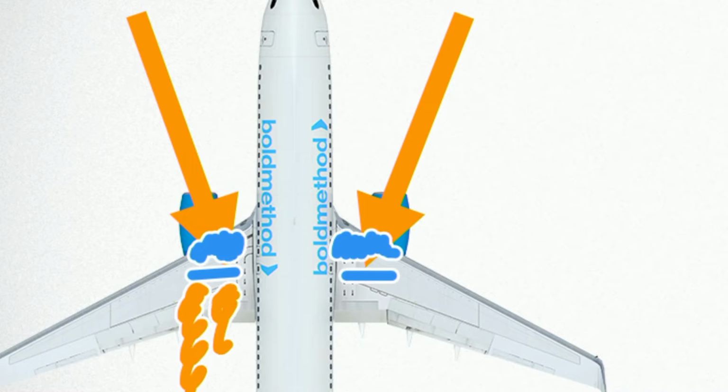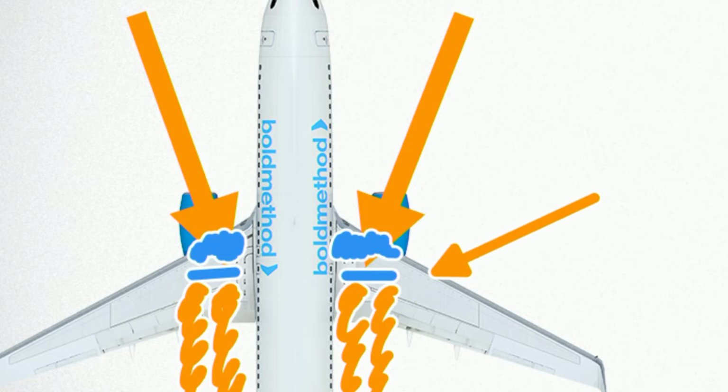But now we have separation happening coming off right here. Well, first of all, this is going to change the aircraft's center of lift. And if you think about it, the root has a lot of surface area. It generates a lot of lift. But now we've cut away a significant part of that. So we've taken away a lot of the lift contribution from the aircraft's wing root. And if you look at the swept back wing, look where it is. It's all behind the aircraft's wing root, right?